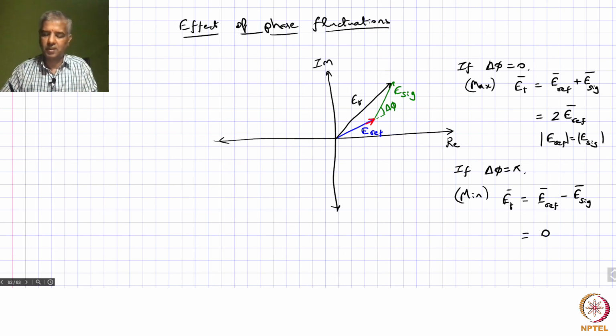The amplitude may also change as a function of time, but more importantly for our application, the noise actually has a random phase associated with it, because the refractive index is varying in a random manner because of environmental fluctuations. So you have this varying randomly, and similarly here also you have a random fluctuation in the phase, right?